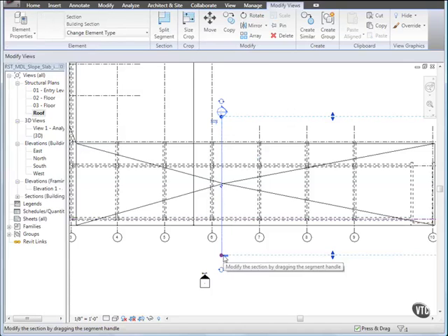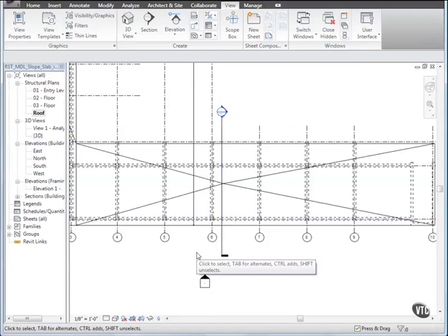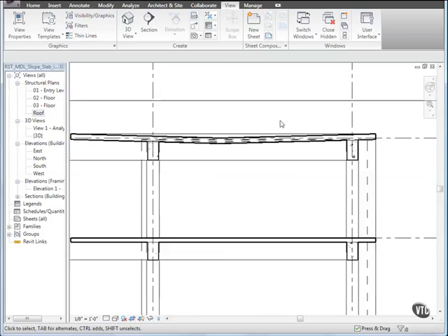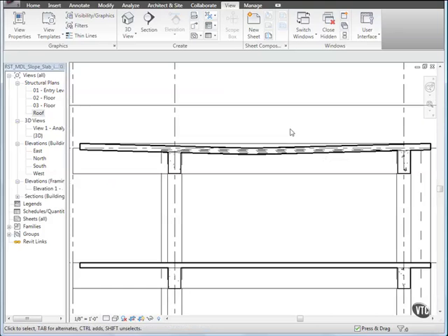Then press Escape, and let's open the section view. To open the section view, double-click the section head and zoom in on the roof. You can see in the section view that the slab is sloped. The design specifies a slab that is flat along the bottom edge and that you create the slope using tapered insulation. Let's modify the slab construction to reflect this design.